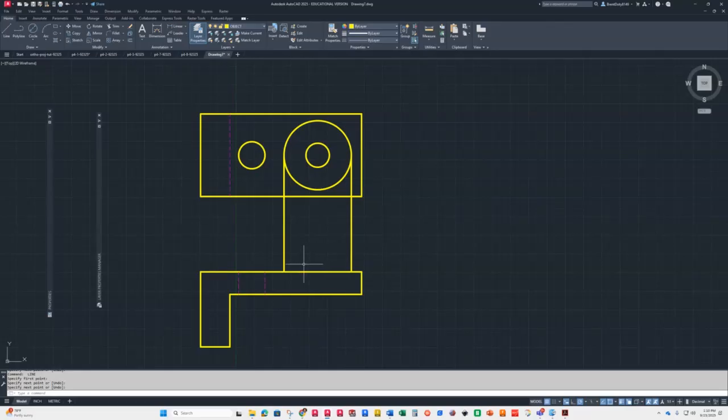And then it says that it is 35 tall off of this line. And I don't need to explode anything, so I can just go to offset, 35, and somewhere, pick. Here we go. Let's see. I'll just do that.